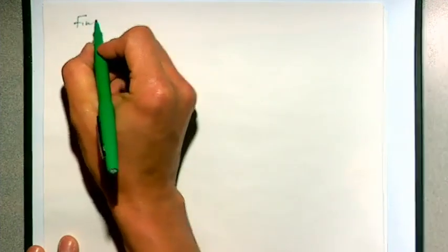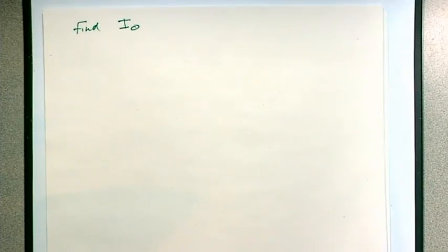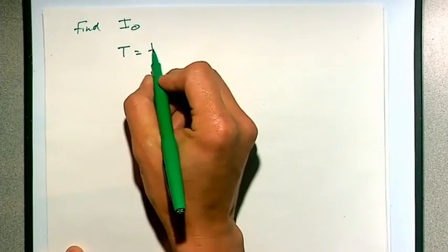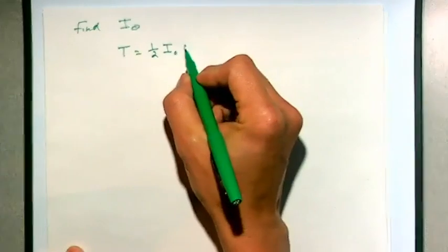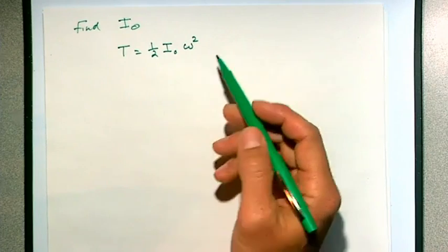All right, so we're trying to find kinetic energy of this system. The first step is telling us, hey, go and figure out I_O. Find our moment of inertia of this composite system about point O. Because then our second step, kinetic energy, is just going to be half I_O omega squared. Right? So if I want to find the total moment of inertia of the whole system about point O first, that's the hard part. Kinetic energy is easy because it's pinned.